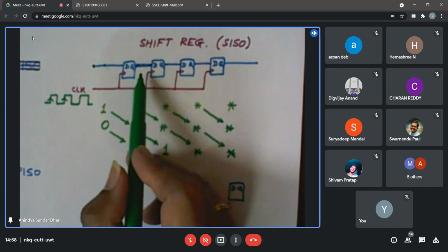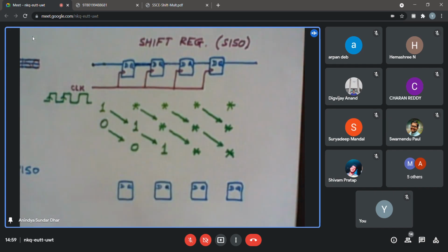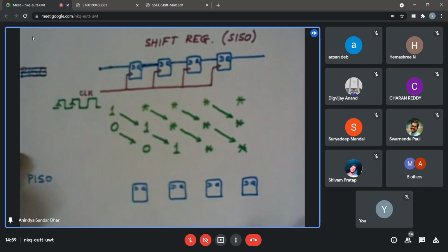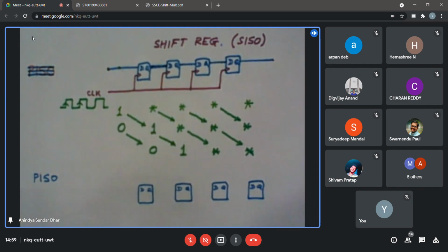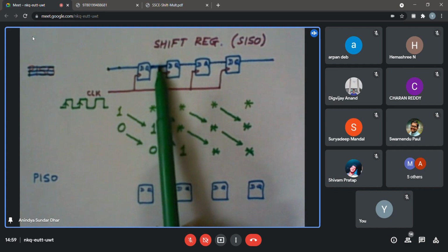So that has to be avoided under any circumstance, that I cannot short the outputs, unless, I think maybe in theory class it has been discussed that something called open collector or open drain output. Are you aware of that? Something called wired AND. Yes. So accepting those situations, I think we are not supposed to connect two outputs. So in general, without going into the discussion of that thing because it will be covered in the theory anyway, as a general rule, we understand that outputs cannot be tied together. So I cannot tie the output of this one with another line which I'll be driving from some other source.